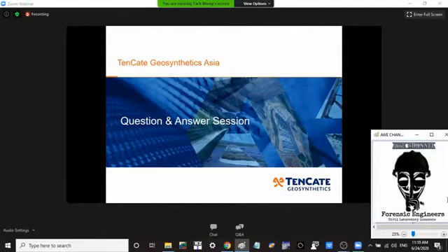the stability is the major problem, and the settlement is small because, say, for example, you have a thin layer of soft clay that can consolidate quite quickly, because when you have a thin layer, then the vertical drainage path is much shorter, and you may be able to tolerate the consolidation settlement after the period.